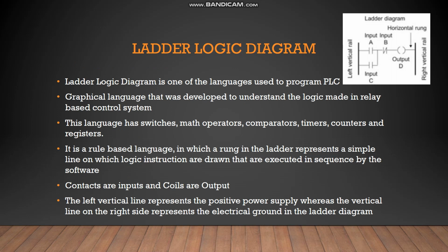Now coming to ladder logic diagrams, it is one of the languages used to program the PLC. Basically it is a graphical language that was developed to understand the logic made in relay-based control systems. Initially it had contacts of switches that mimic the opening and closing of relays, but now this language has included several operators as well.